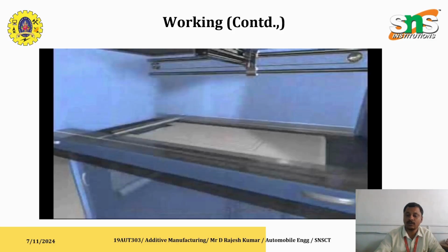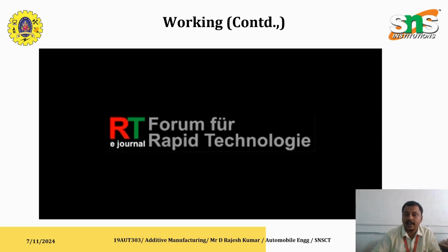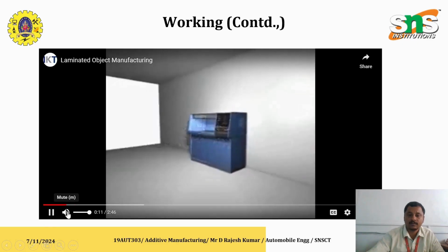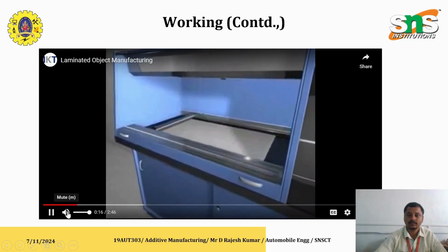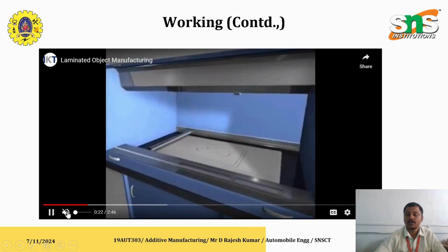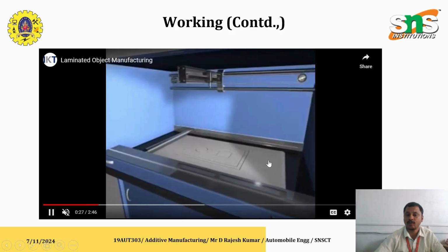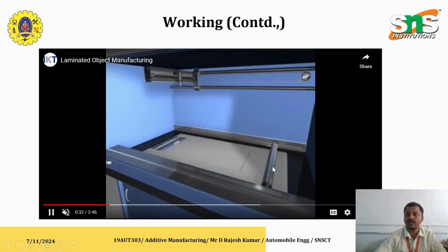This video shows how the material is processed. A laser provided at the top scans the material according to the geometry given in the CAD model, and it cuts the material. Again, the roller feeds. This action is continued. We can watch this action.